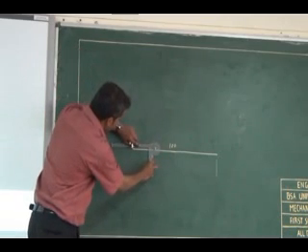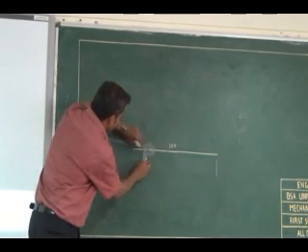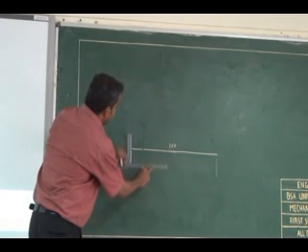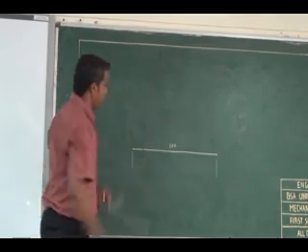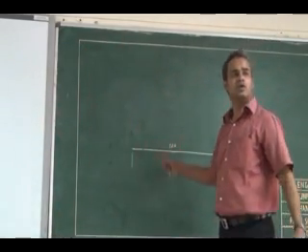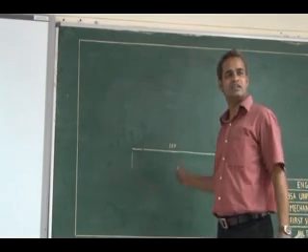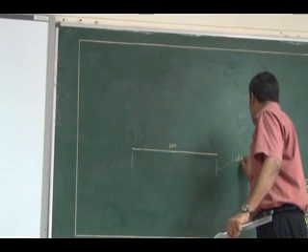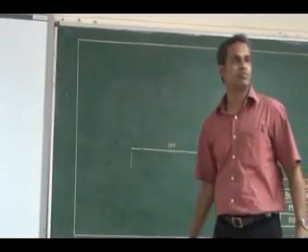Similarly, I can move my drafter here and align it to the object which I am dimensioning. I can move it like this and draw an extension line. You see, these two lines which I have drawn perpendicular to the entity at its ends are called extension lines. All your dimensions will have extension lines.